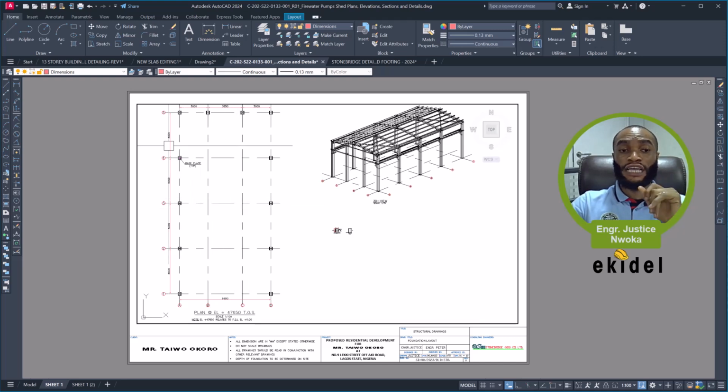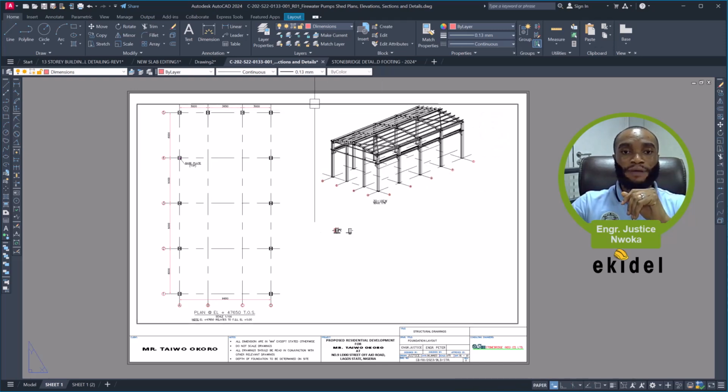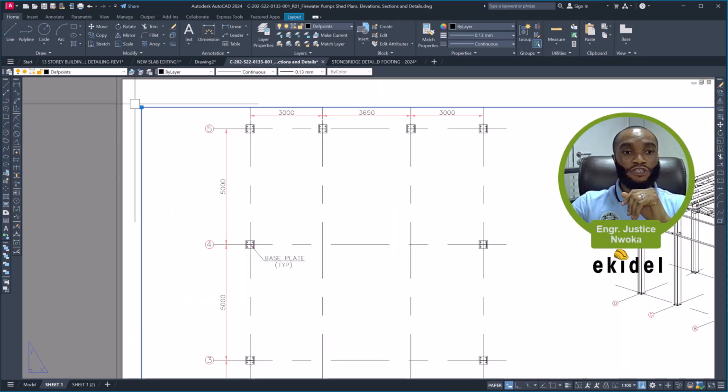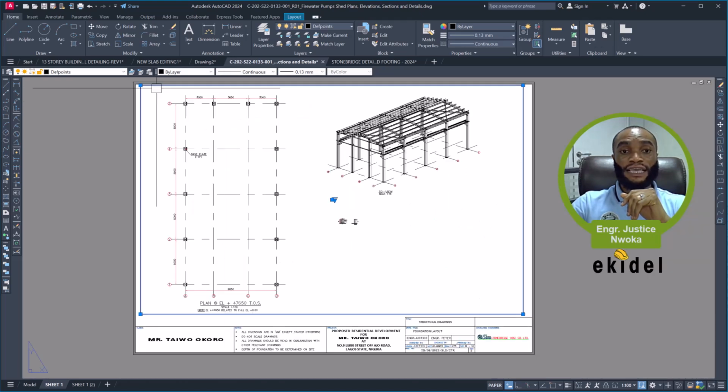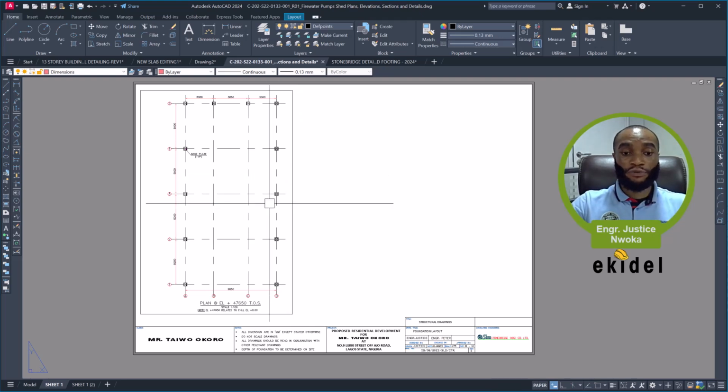Okay, that's fine. You can see there are still some parts which are meant to show, so I'll not zoom. I'll type PS. PS is to go out from the viewport. Then I will expand my viewport space, something like this. That's fine. Then I'll reduce this viewport, because that scale was just for this particular drawing. You can see that I have now put this drawing in this place.